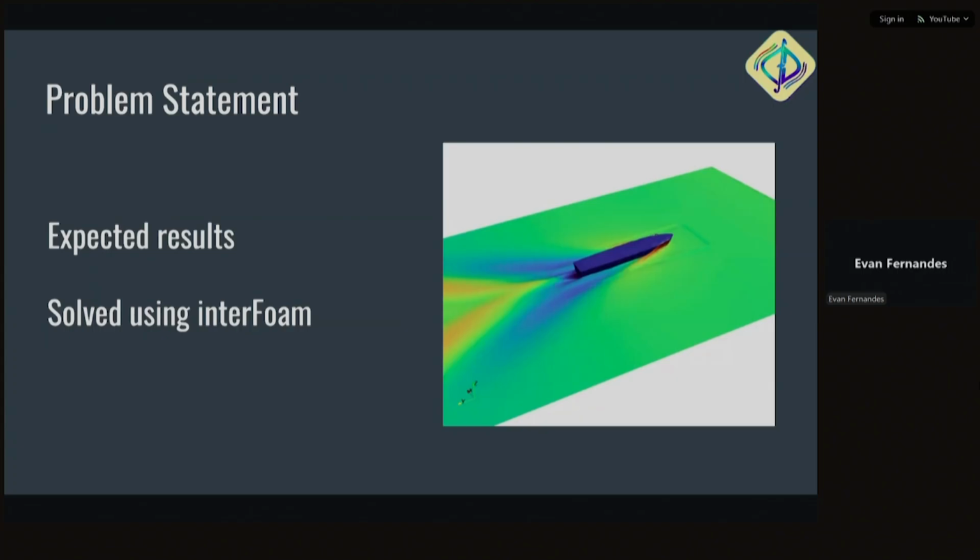We will also see various ways to post process your data. You can do it using Paraview, or using a custom Python code as well. In the case study itself, you have a custom Python code implemented. At the end, I'll also show you another way in which you can write your own code and find out any data that you want using that custom Python code.